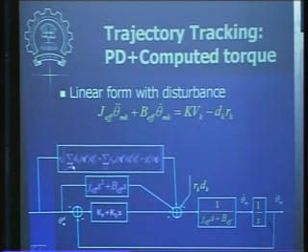Remember this J not equal to K, all the coupling terms in the inertia matrix, then Coriolis and centripetal acceleration terms, and then your gravity term. Okay. So this multiplied by RK will form this computed term, and then you will find now that your error